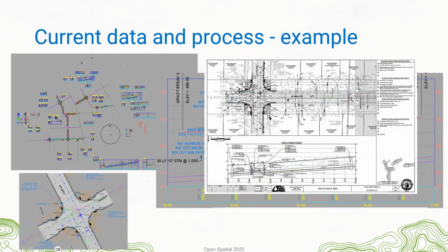And so this is the result of where we go, and that'll get marked up even with red lines. And you're going to need to tell folks, no, we don't want the PDF. You can give that as well. We want all of the markups in the CAD drawing that you use to create this PDF, and we want those as an XREF drawing just for the disciplines we're interested in. So if you've got water, sewer, storm, or cadastral or easements, try and keep each of those in its own XREF drawing, and they can still make all of this. It's just then they can also give you each of those individual drawings, and you can validate those and send them to different departments and etc., that sort of thing.